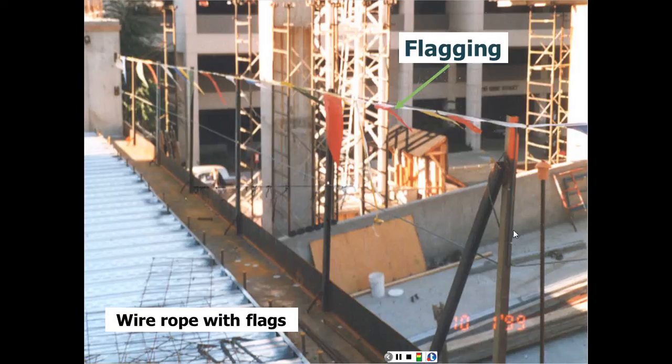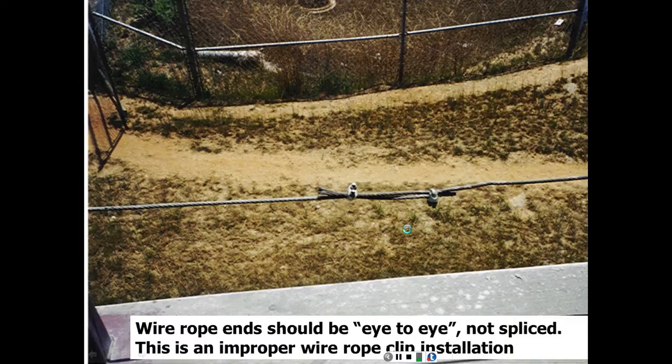This one probably is a better one. It's properly flagged, and as you can see, with different color flags, so it can be seen from a distance, and it has enough tension. Most likely it's not going to deflect more than 3 inches. And we have the toe board, we have the mid line as well, mid rope.